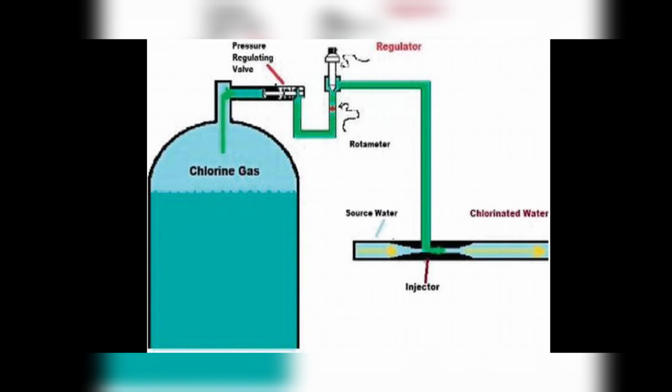Disinfection. Once the water has gone through the filtration process, it is about as clear and clean as it can get. However, there may still be bacteria and viruses remaining. To ensure these are destroyed, there must be a disinfection process employed. The most common disinfection process used in the United States is chlorination. Chlorine comes in many different forms including chlorine gas, chlorine dioxide, hypochlorite and others. Whichever method is used, chlorine is added to the water in an amount to ensure all microorganisms are destroyed.